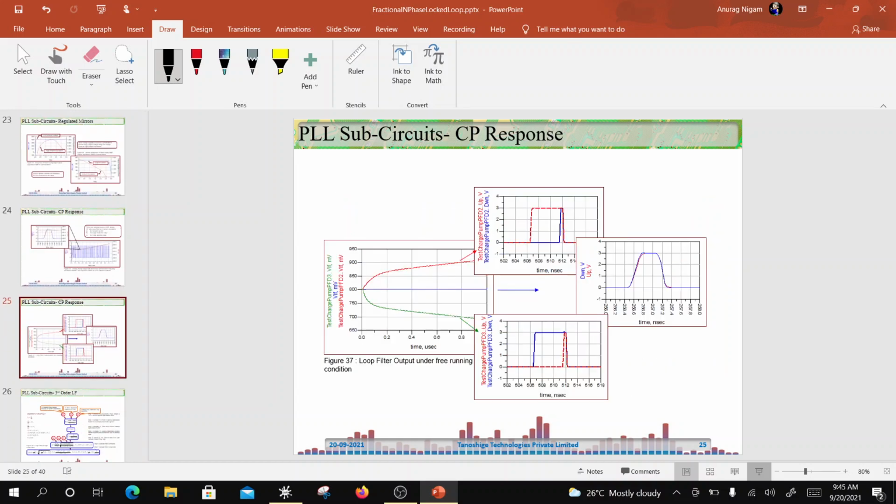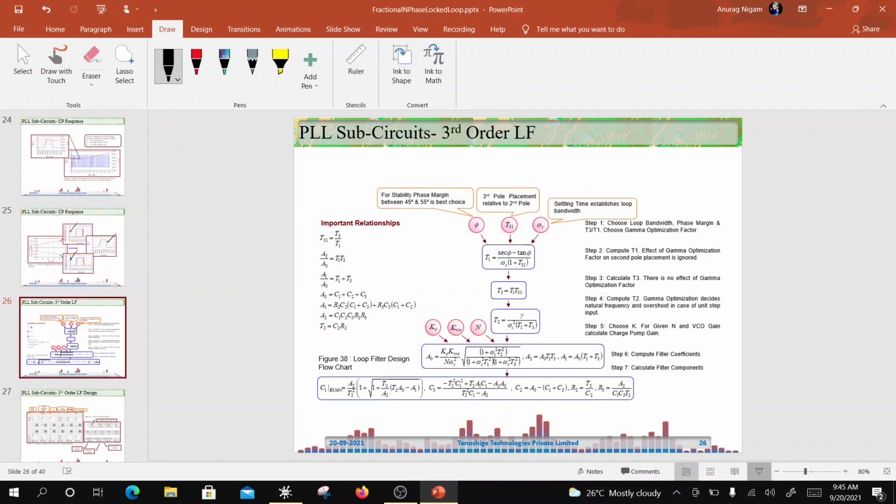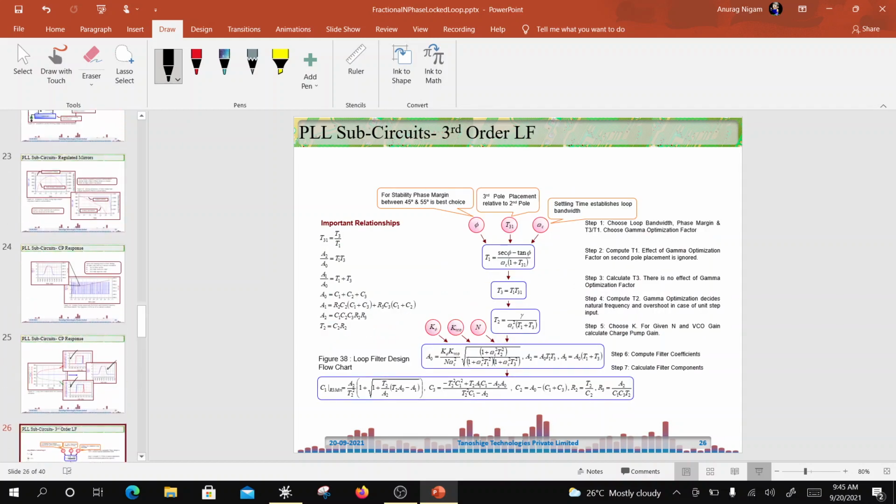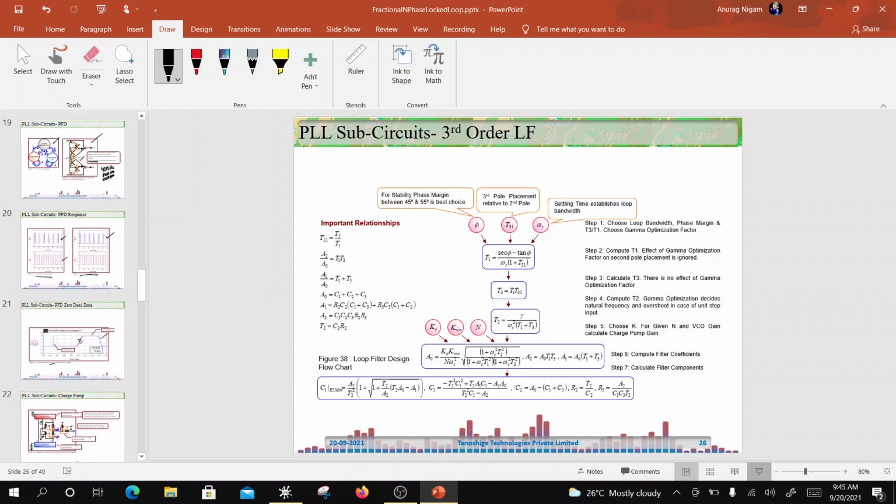So here I'm just showing you source and sink impedances, and here I'm showing the buildup of charge pump voltage, right? So if I look at the two conditions, up and down, then you have the red one which is pulling this up, and the green one, basically the down pulses, are pulling it down, right? So these are the two cases here. And then when both are matched, up and down come for a very short duration, they come together, right? So that represents this flat voltage, or the final voltage, or the steady state voltage. And then I'm going to discuss this loop filter later on. So let's go ahead and design a PFD.